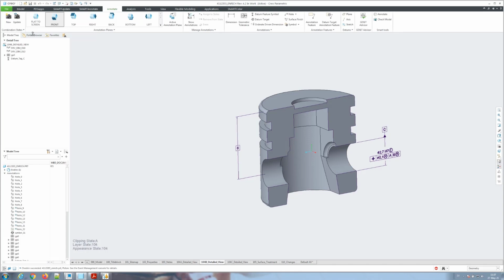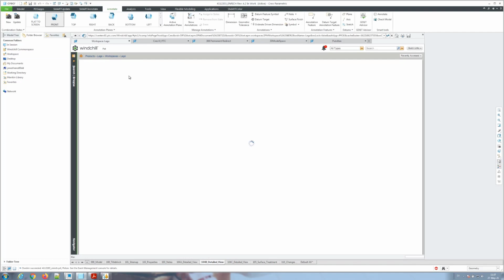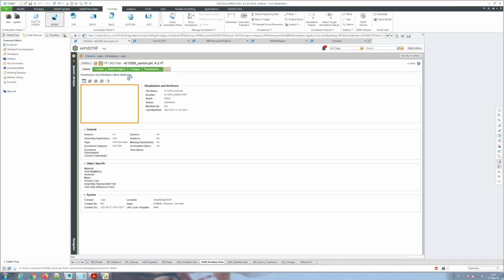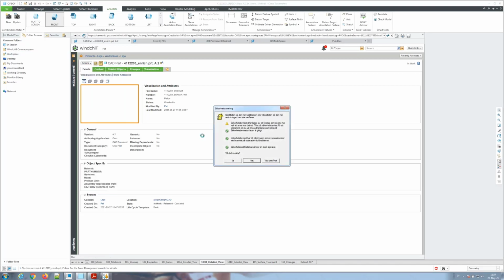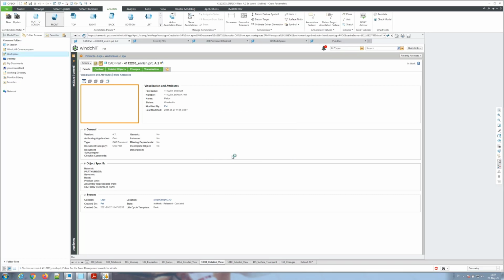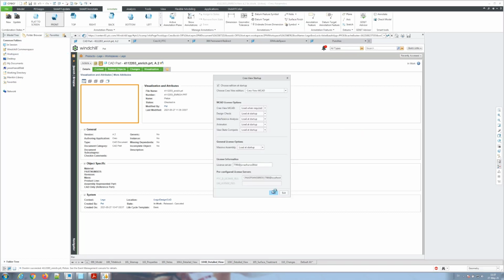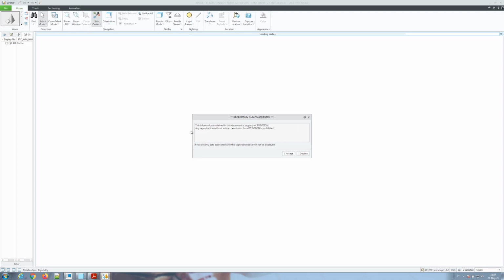When the model is checked in, I can go to my workspace again and view it in Windchill. I've configured my worker to publish an MBD compatible representation of this. So what I basically do is open that one in Creo, and this is the base for a technical data package. This one, together with maybe the BOM document, the STEP file, whatever we need in order to describe it, could be a technical data package.